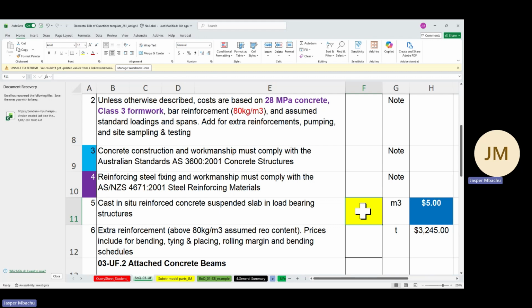We want you to live link it from the worksheets of the quantities you've extracted, the Revit schedule that you've extracted, integrate it here, and within that worksheet, do any takeoff, additions, reductions or removals that you need, and then live link those quantities to here, which is actually what we're going to do. So we know that our remit is to get the quantities extracted that pertain to upper floors and put them here.